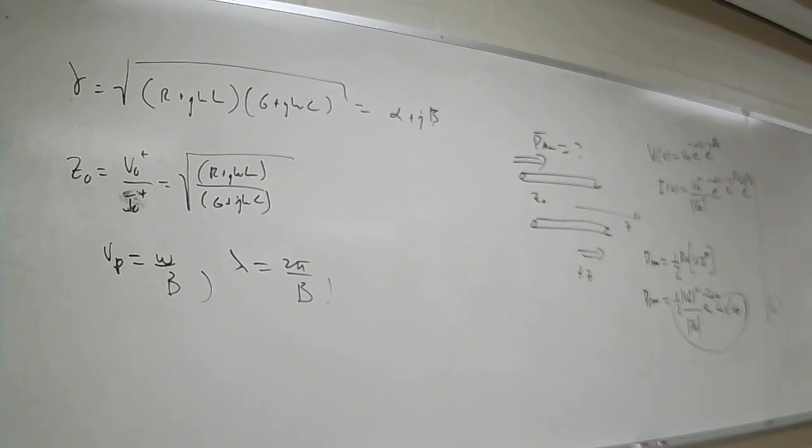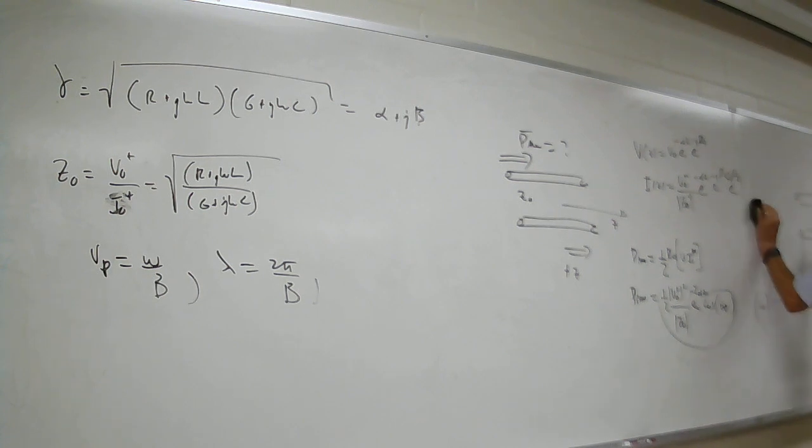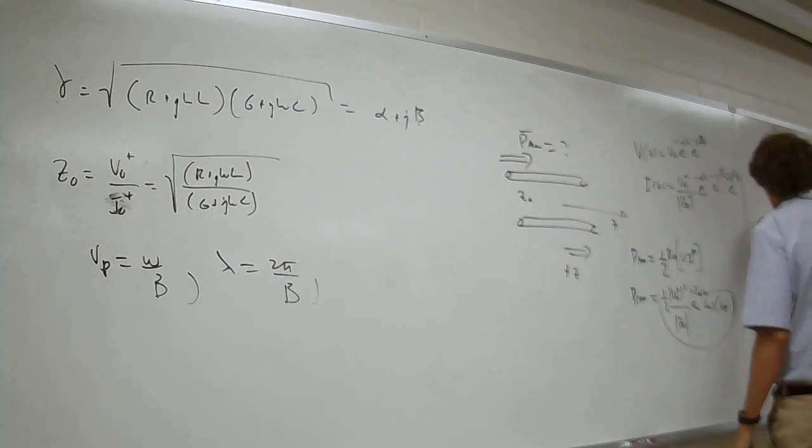And for a wave propagating in a positive Z direction, what we can say, and I'll just draw this, if we have a transmission line as such here, then we'll call this Z equals 0. And this will be positive Z this way. Then the power flowing at Z equals 0, this would be P of Z at any point down the line. It would be average power, equal to some P0 e to the minus 2 alpha Z. And P0 in this case is just going to be 1/2 magnitude of V naught squared, magnitude of Z naught times the cosine of the phase angle.